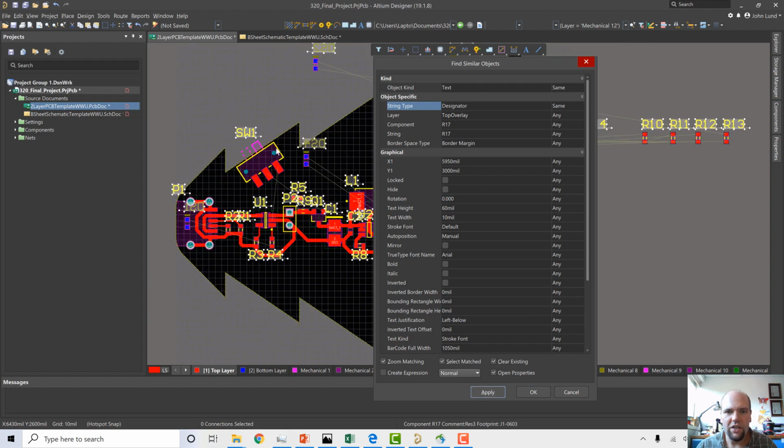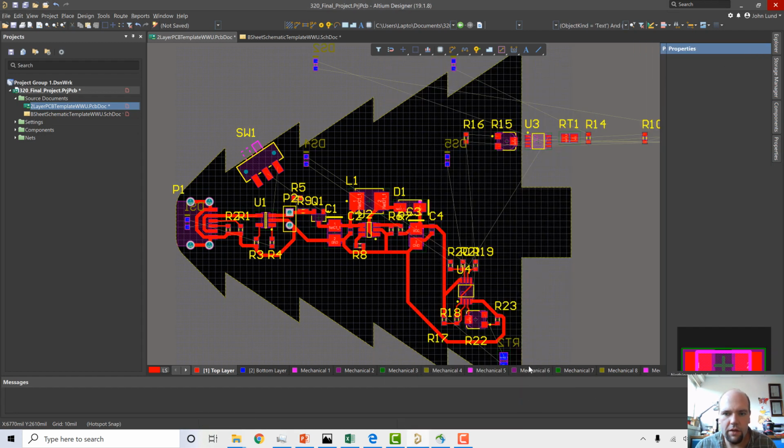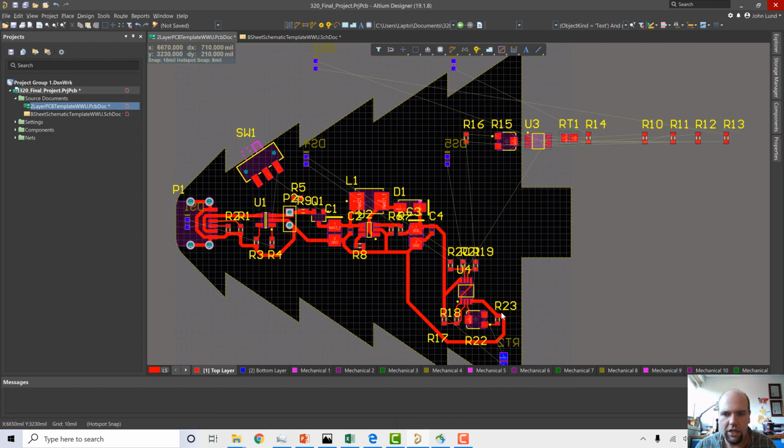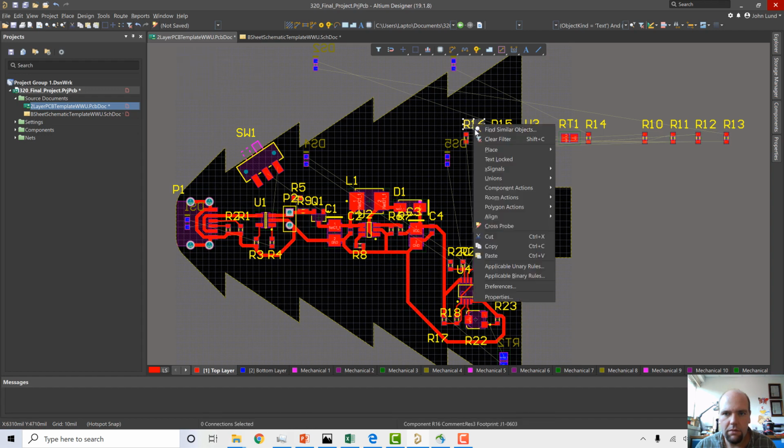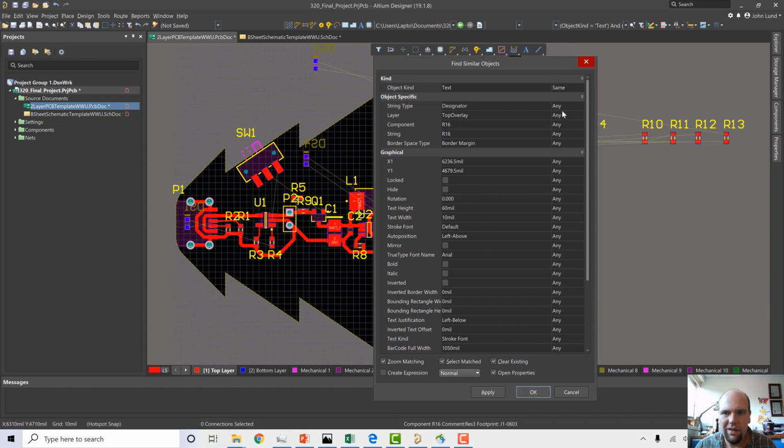So I'm going to select every single one of these annotations. When I do that, it pops up this sort of editor here. It doesn't have to be 60 mils high. These can be 30 mils, and their width can be 6 mil. I much prefer that. Did it change them? I don't know what I did wrong.